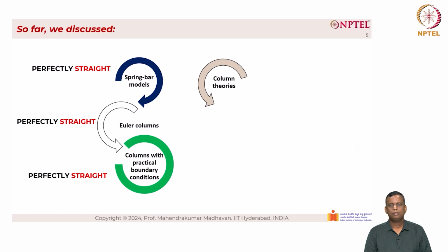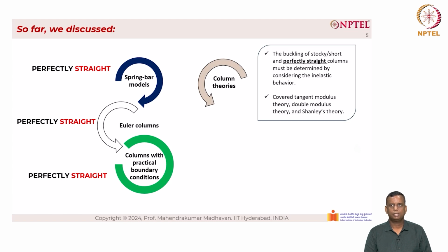After that, we continued our conversation on column theories. The buckling of stocky and short columns, which are perfectly straight columns, must be determined by considering the inelastic behavior. We covered tangent modulus theory, double modulus theory, as well as Shanley's theory. This again was considered as perfectly straight.